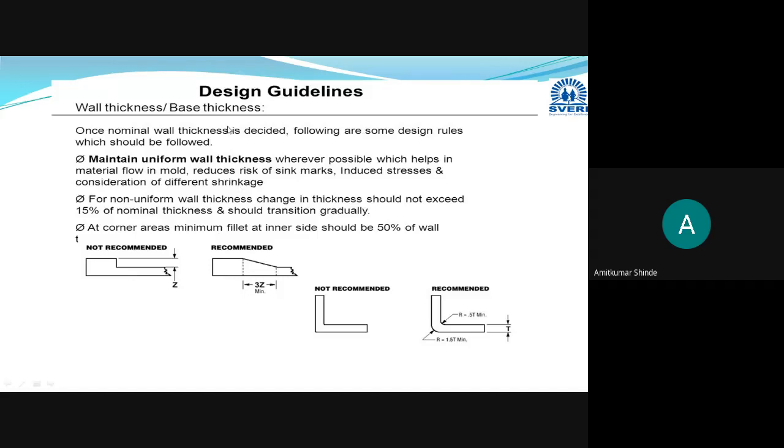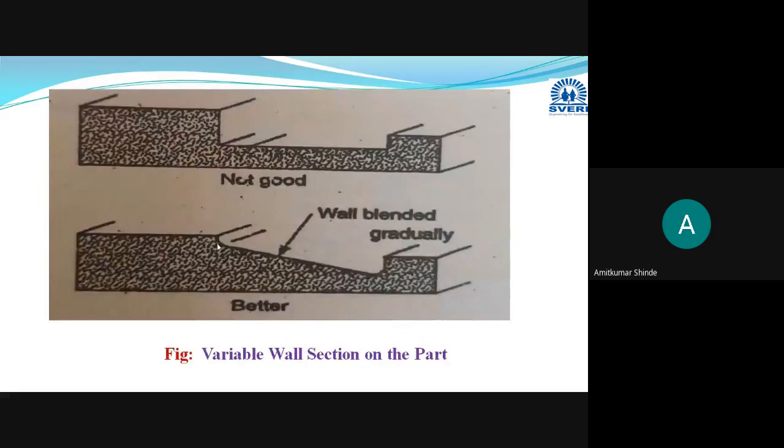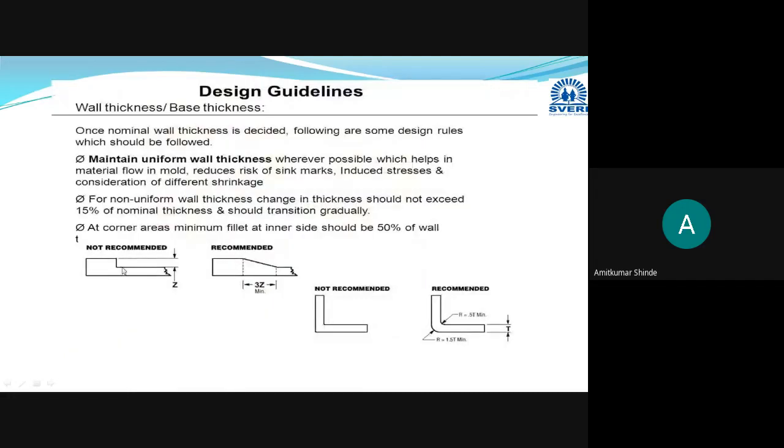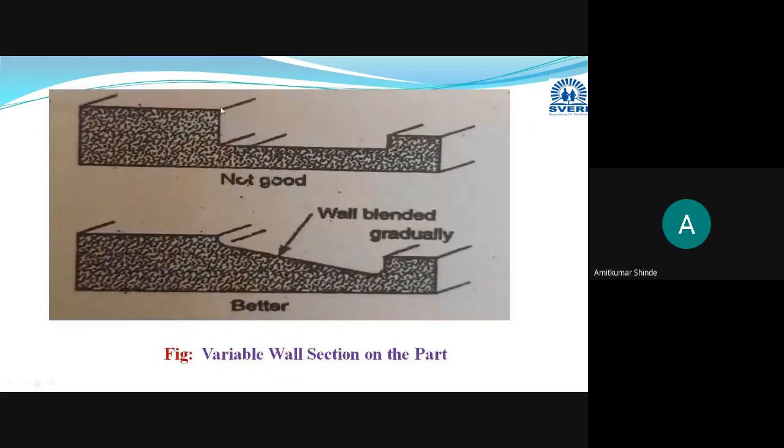Why is it not recommended? Some stresses may get created whenever we are having these corners. The same diagram is there, you can refer to this diagram, or if it is better visible, then you can understand here only. Here you can see that due to these sharp corners, more stress points will be there. The stress points may result in cracking also.